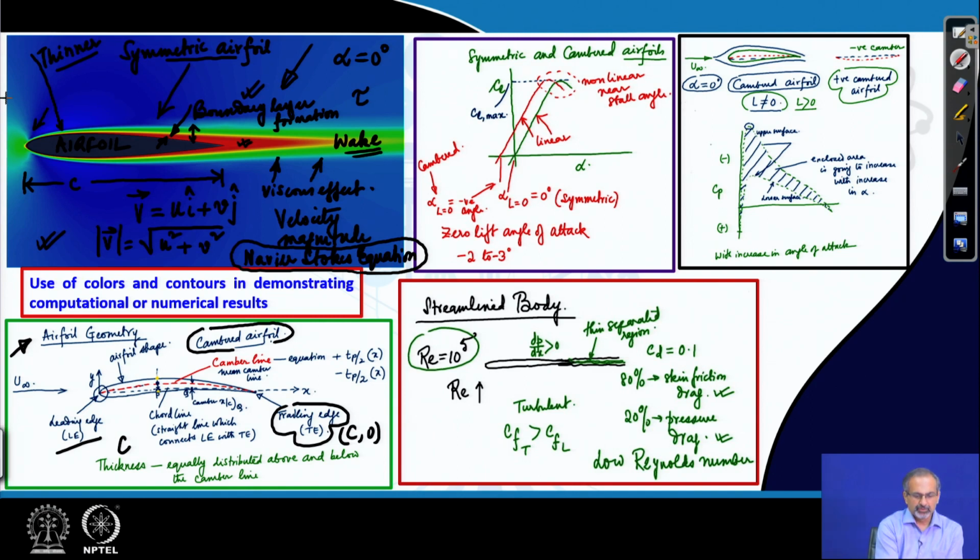And also we can make out that the flow is numerically set in such a manner that a uniform flow is approaching the airfoil from the upstream direction, and it is impinging on the airfoil. Close to the leading edge of the airfoil, the velocities are becoming very small, and you can imagine that close to the leading edge you have the stagnation region. There is a specific point, which is the stagnation point, where you can expect the flow to come to a halt.